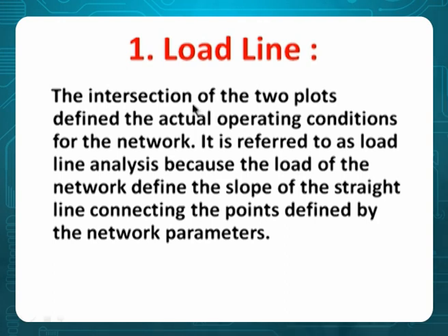Why do we need a load line? Why is it called load line? Normally, load is kept at the output, because whatever we drive is called a load, and therefore it has to be located on the output characteristics. So why do we need an actual load line? Without load line, you cannot have a direct relation between output voltage and output current.